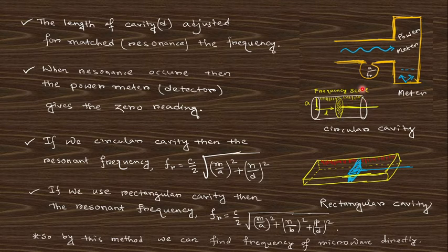How can we see this total power will be 0? In this meter we can see the total power is 0. That means the power does not reach this meter. Then what happens? The power is trapped, or the resonance is matched with this cavity. That means the frequency of these two is matched to the incident microwave.